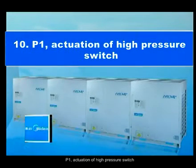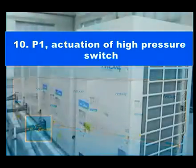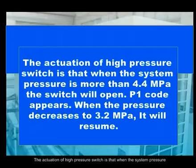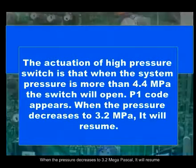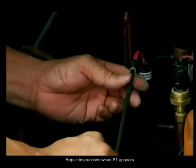P1. Actuation of high pressure switch. The actuation of the high pressure switch is that when the system pressure is more than 4.4 megapascal, the switch will open and the P1 code appears. When the pressure decreases to 3.2 megapascal, it will resume. Repair instructions when P1 appears.